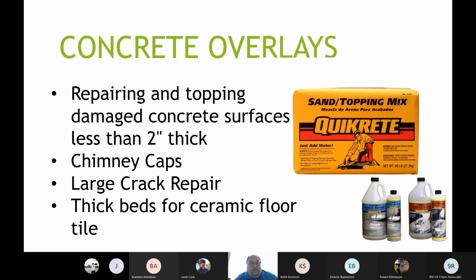Some of these faceting products, like that facet repair mortar, if you put hot water in there that you got out of a hose, you're gonna be rolling a bunch of boulders around in a bucket. You won't even get it on the ground. It'll be set. So use colder water on hot days. It delays the set. There's little tricks you can do like that as well.